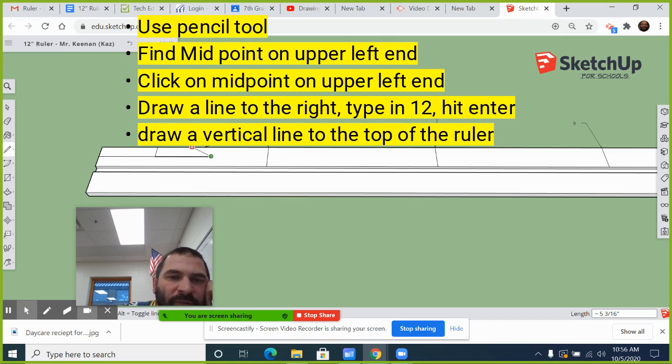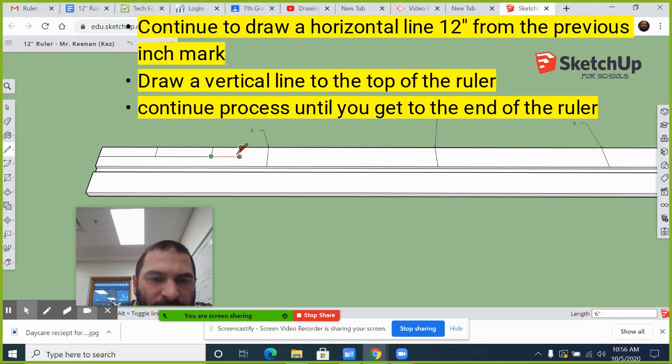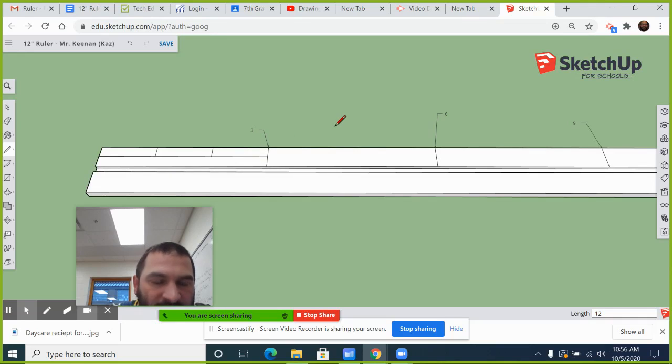The reason we're doing that is so that it's blown up really big so we can see it as we draw it. It's just the way we're doing it. And if we did this correctly, from here, 12 inches should end right at 3. And it does. I'm going to hit Control Z because I don't want that one. Maybe at the midpoint of this one, I'm going to move over 12 inches, enter. Even if this doesn't make 100% sense to what we're doing, just try to follow along as I'm going.